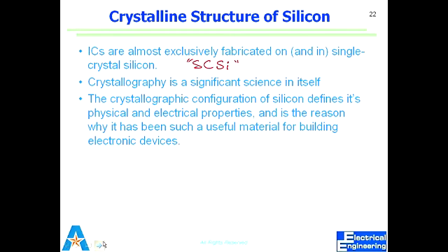So you could actually make lines with heavily doped polysilicon, and they will act like conductors. And now I can do heavy thermal process. You could put them in your 800-degree furnace, 800, 1000, 1100, whatever. It will get oxidized, right? But not at the same rate as single crystalline silicon, because single crystalline silicon has a certain density of atoms available for oxidation, reaction with oxygen, and polysilicon is entirely different.